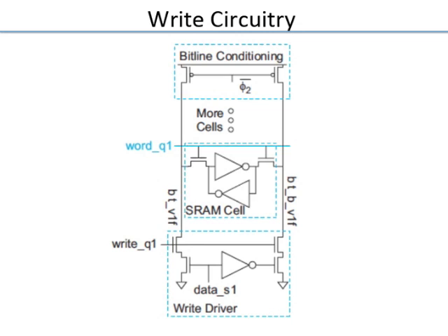So we can have write Q1, and similarly instead of that we can have read Q1 added to the pull-up structure. If you do that, then for a write, because you also have to pull up the bit line to 1, one of the bit lines has to go to 1, the other has to go to 0. So then you need to put in the PMOS structure out here, which is duplicating the area. That is why you want to have a single precharge and a pull down happening either from the memory or from the write.